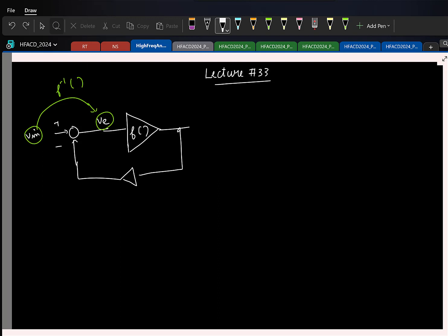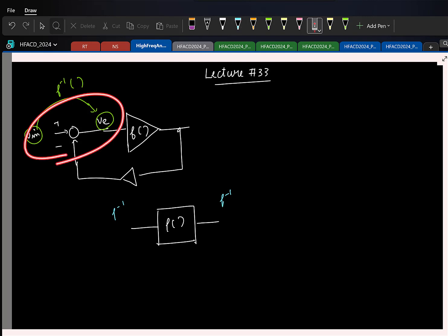As I mentioned, this is a normal thing that we typically use to counter nonlinearity. If you find something to be nonlinear, one way to counter it is you somehow estimate this nonlinear function, put an inverse nonlinearity before or after this to counter it, and when you use negative feedback, it kind of does it for free for you.